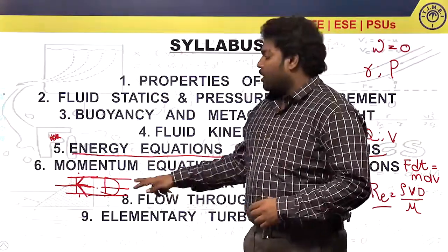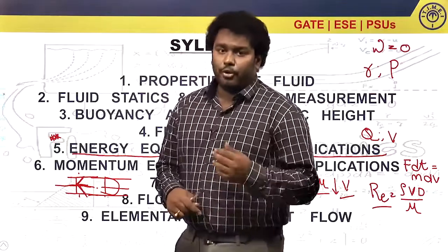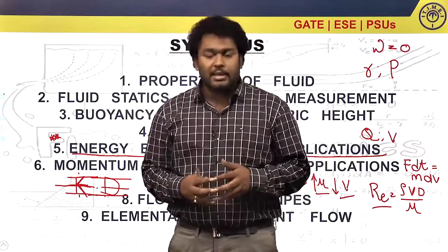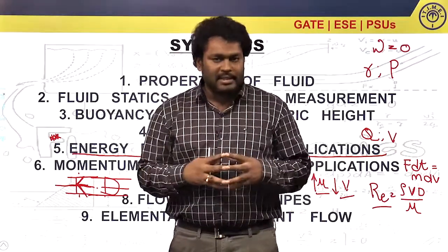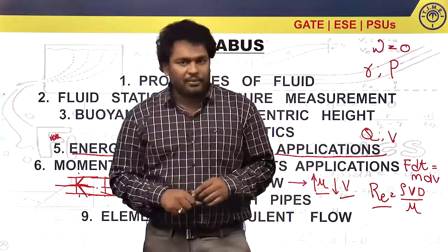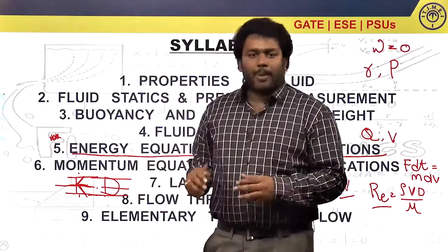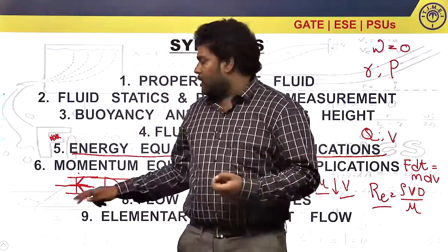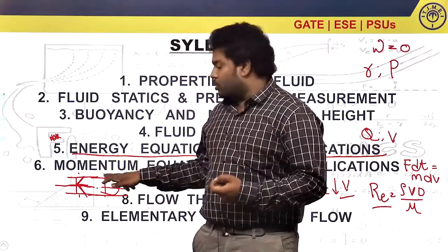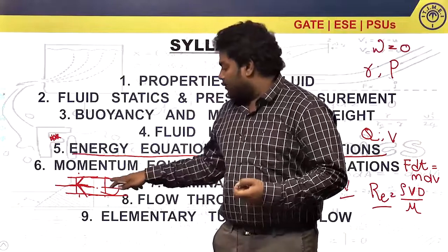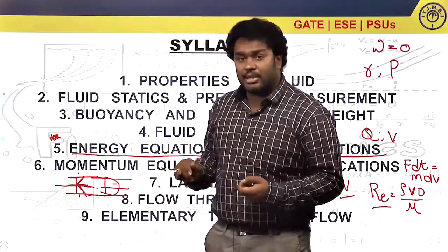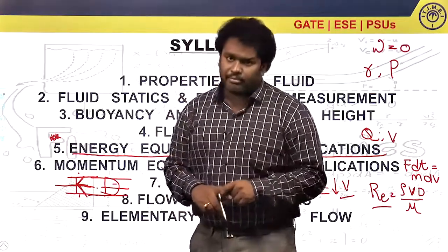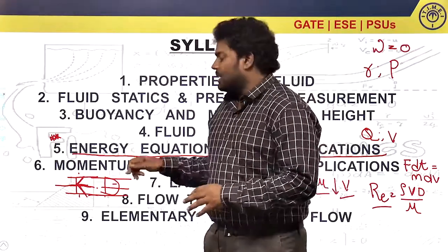The next will be velocity profile distribution. Whenever the fluid is moving, it will have some velocity of the particles. We will see how the velocity of the particles is distributed in case of laminar flow. Generally, it will be a parabolic development in the flow. The shear stresses will be maximum at the corners, where the velocity is zero, and the velocity is maximum at the center, where the shear stress becomes zero. In the parabola, this is the center line velocity where you will have the maximum velocity for the fluid particles. This is regarding the laminar flow.